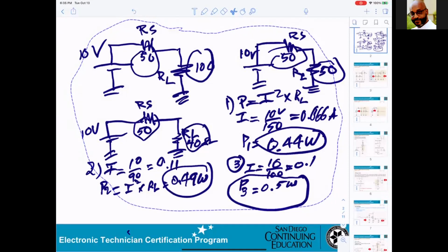They're not loading that signal from the generator. So if you say 5 volt peak to peak, you get 5 volt peak to peak. If you get only 2 volt peak to peak, that means your circuitry has a problem. It's loading down the signal from the generator.